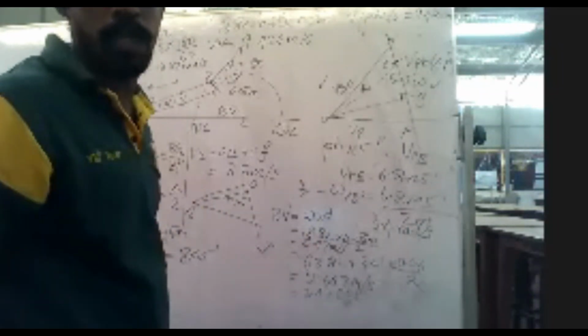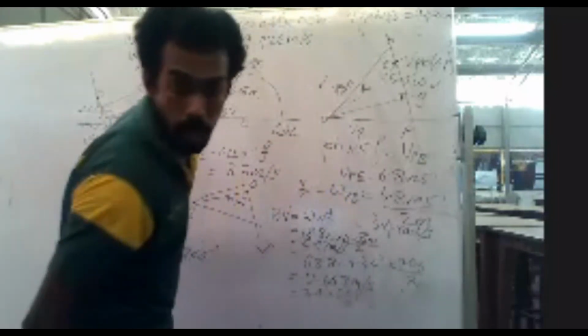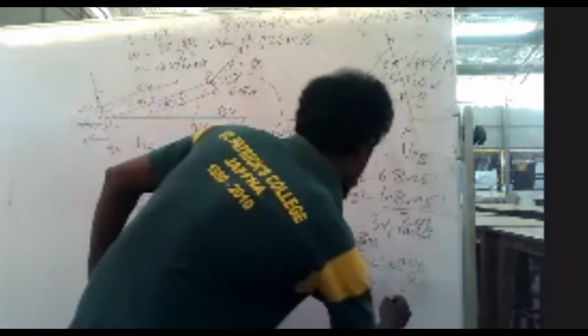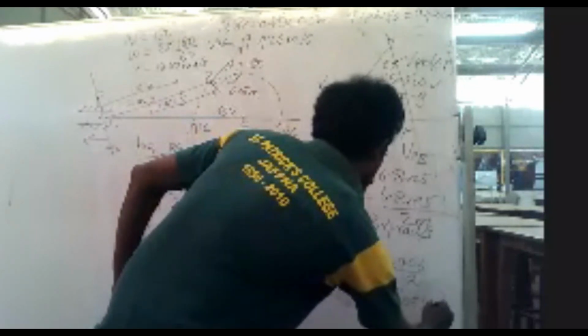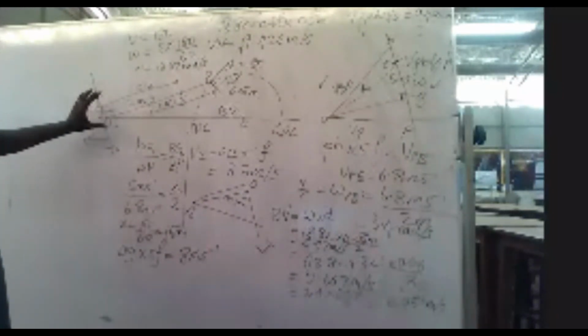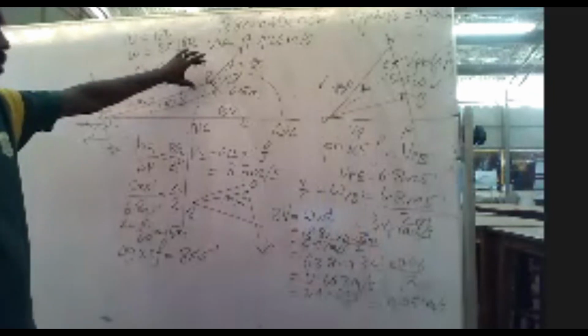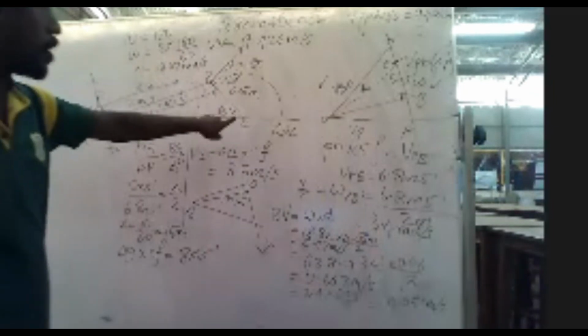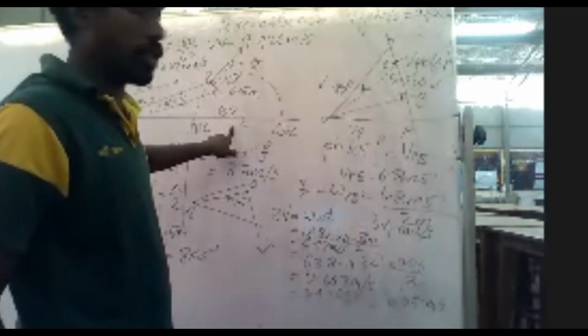The diameter is given, I have to go for the radius, right? Which will give you 0.051 meter per second, right? So this is the rubbing velocity of point P, 0.051. Rubbing velocity of point B, that is 0.667, and rubbing velocity of the crankshaft, which is 0.47 meter per second.